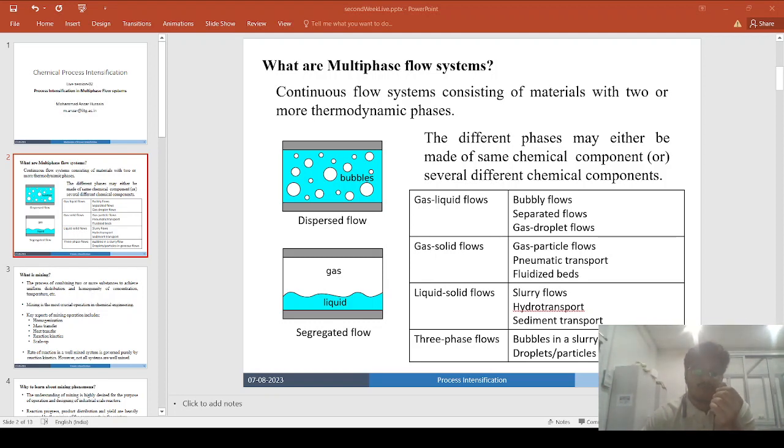And now what are the common features of the reactive absorption, reactive distillation, and reactive extraction processes? The common feature of the three of them is that they involve at least one liquid phase. In the reactive absorption you perform the reactive separation using a gas liquid multiphase system, in the reactive distillation you use a gas liquid system, and in the reactive extraction you use a liquid liquid system. So in all of these three systems you involve at least one liquid phase.